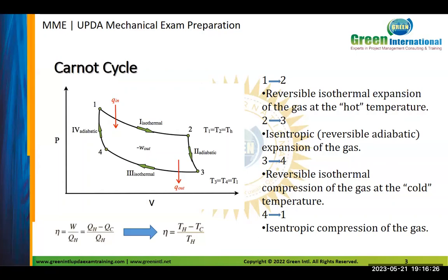You should be aware of the enthalpy for the first point and the enthalpy for the second point, okay? For special cases like the cycles where the medium is air, which falls under the umbrella of ideal cycles, the medium here is an ideal gas. So for ideal gas cycles, we can represent the enthalpy with temperature. As per Joule's law, the enthalpy is a function of temperature only. This is the normal sequence we know. Okay. This basic is important.